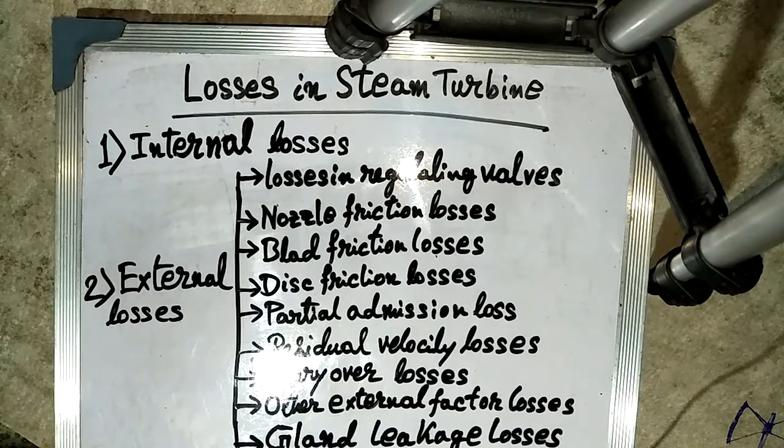As the steam, before entering the turbine, passes through the main valve and the regulating valves, the flow through these is accompanied by pressure losses, and the steam gets throttled adiabatically with constant enthalpy. However, the enthalpy drop in the turbine decreases, yielding less specific output. Thus, some adiabatic energy of the steam is lost due to the irreversible process of throttling. This pressure drop varies from 3 to 5% of the inlet steam pressure.